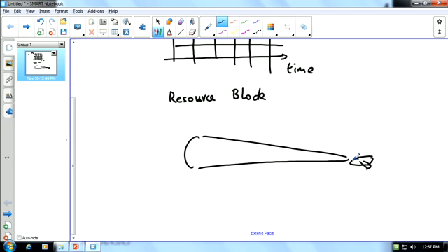And the antennas, in order to get a stronger signal, will focus the beam of the signals to the location of the aircraft. But the aircraft is moving, so we need to use phased arrays. Many of you might have heard the term phased array antennas. We can control the phase, such that the beam can be steered into different directions. And when the aircraft is moving, the beam can follow this aircraft. Okay, so that's how the radar is tracking the aircraft or the missiles.